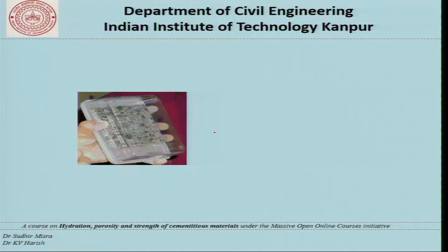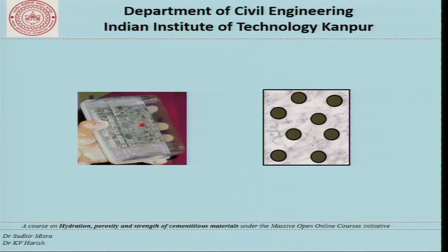Now, let us look at this picture once again, where we have coarse aggregate particles suspended in mortar, and then we cannot see the suspension of fine aggregate in paste. But what we can do is model this in this form, and say that concrete is a suspension of these coarse aggregate particles in mortar. And at the mortar level, this is basically fine aggregate particles in paste.